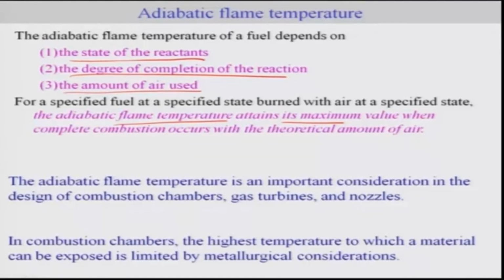This adiabatic flame temperature becomes an important characteristic because it has to be considered in the design of the combustion chamber, gas turbine and nozzle. It is important for the metallurgical aspect of the combustion chamber. In a combustion chamber, the highest temperature to which a material can be exposed is limited by metallurgical considerations. So you need to be aware of the adiabatic flame temperature, that is, the maximum temperature a reaction can yield, or the product can reach.